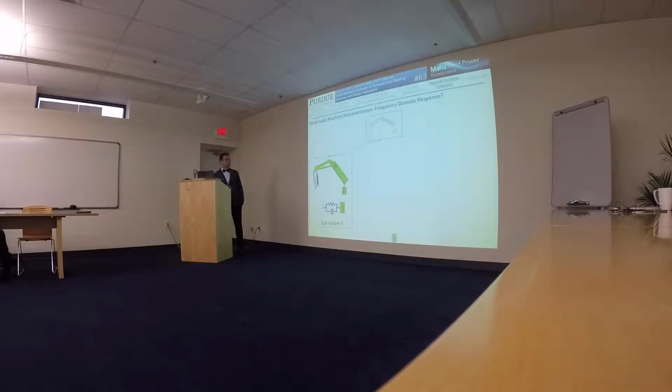So the first subsystem can be represented by the main boom actuator with the rest of the machine, which can be modeled as an equivalent mass acting on the cylinder. The second subsystem is the outer boom actuator with the rest of the machine, again acting as an equivalent mass. And the third subsystem is the payload itself.